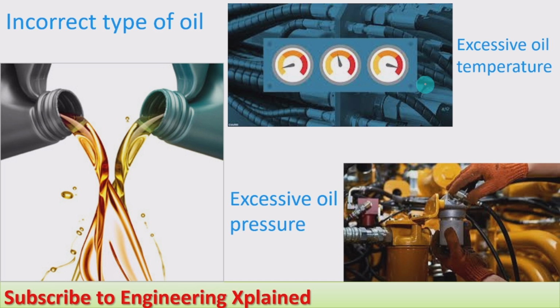If the temperature keeps increasing for the continuous operation, then that excess temperature will cause breaking of the lines or some leakage and damage to the seals, like that it will take place, and that is the excessive oil temperature, one of the causes for the failure of the system. Then last one, excessive oil pressure.